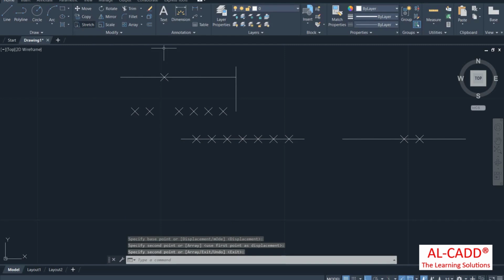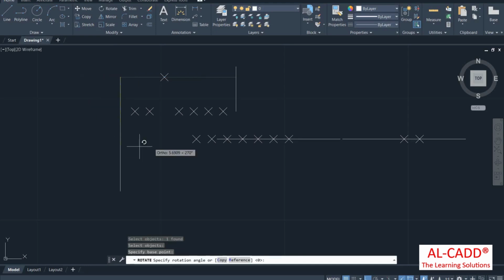Okay. So stretch stands for STR. Just select this line and you can enter and you can stretch. Okay. So next rotate stands for RO. RO, enter, click the line and enter this point and you can rotate whichever the angle you wanted to rotate. So mirror. Mirror stands for MI. Enter. Now so same object, if you wanted to mirror, then you can click on this and you can draw this. So object will get mirrored.